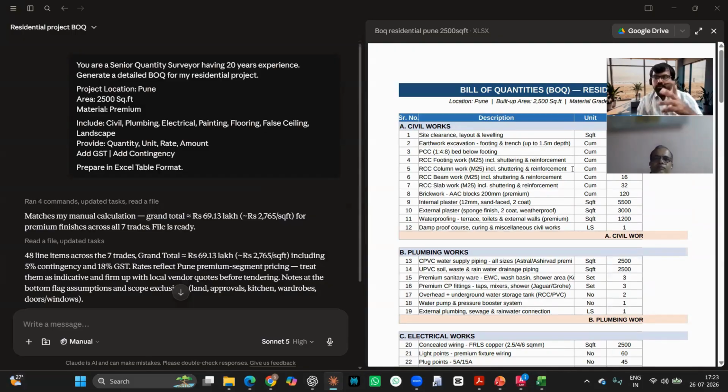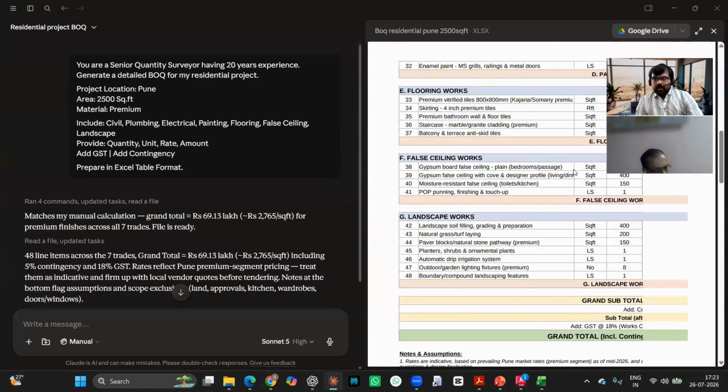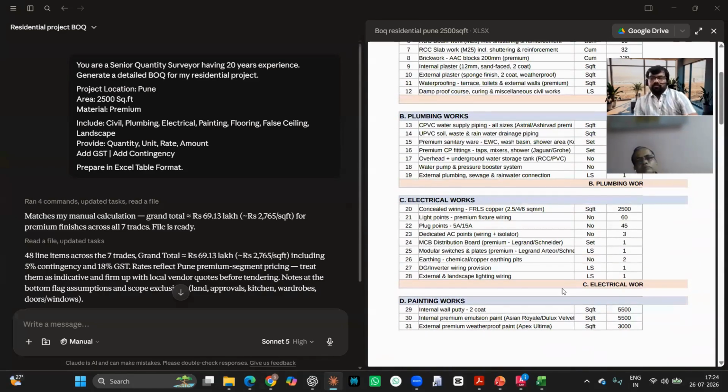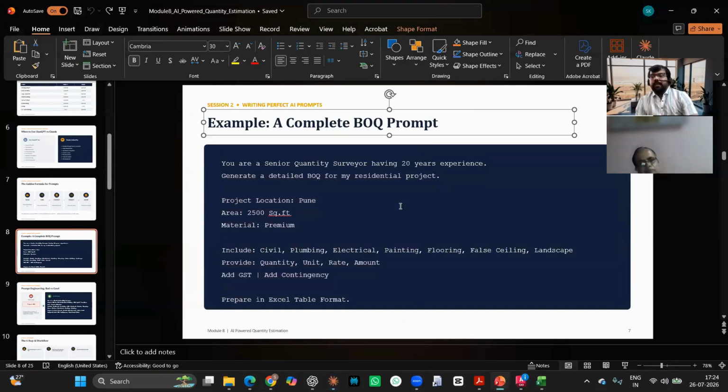So 1.5 to 2%, and if your structure is very heavy, it will go beyond 3%. Sometimes it is 1.5 to 2.5%. This reinforcement cost will be required for the RCC construction. So that is the thing you need to adapt. Another point is that this is a total BOQ for any bungalow construction. Before tendering, at the proposal stage of a project, that BOQ will be applicable, no doubt.